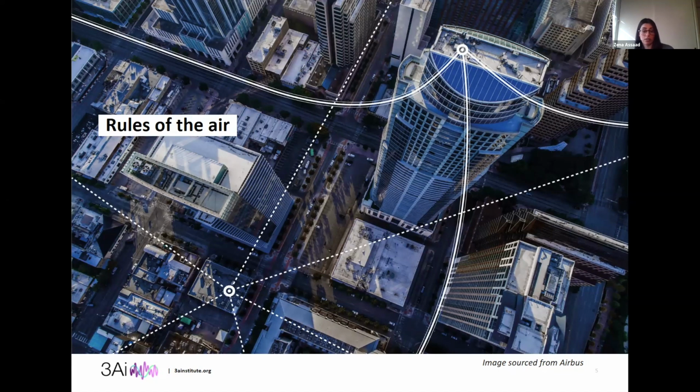Translating this over to unmanned aircraft, flight plans can carry the same purpose, but perhaps be delivered in a more autonomous way. It's essentially planning and announcing flight intentions. So if an unmanned traffic management system is going to be autonomous, this pre-prepared information will be crucial for safe flow management. I will note though that while there is an existing format for current flight plans, I think that this format will have to be changed to fit the needs of unmanned aircraft and to provide relevant data for an unmanned traffic service. This data set may potentially look quite different for unmanned services in comparison to the data set for regular passenger transport.